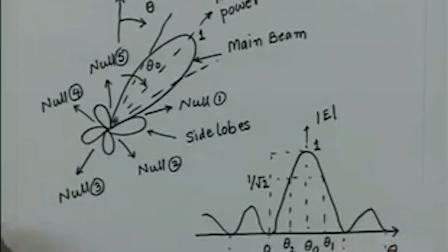However, as we saw earlier, a radiation pattern is normally taken like a 2-dimensional figure by taking sections of the 3-dimensional actual radiation pattern, and these 2 radiation patterns we called the E and H plane radiation patterns. Same thing we can do for a general radiation pattern also. We take 2 sections, one by a plane which contains the electric field vector, and the other which contains the magnetic field vector. If I take these two sections, I will get the half power beam width from the two planar radiation patterns which I get by sectioning the 3-dimensional radiation pattern. So, I can get this half power beam width in these two principal planes, E plane and H plane.